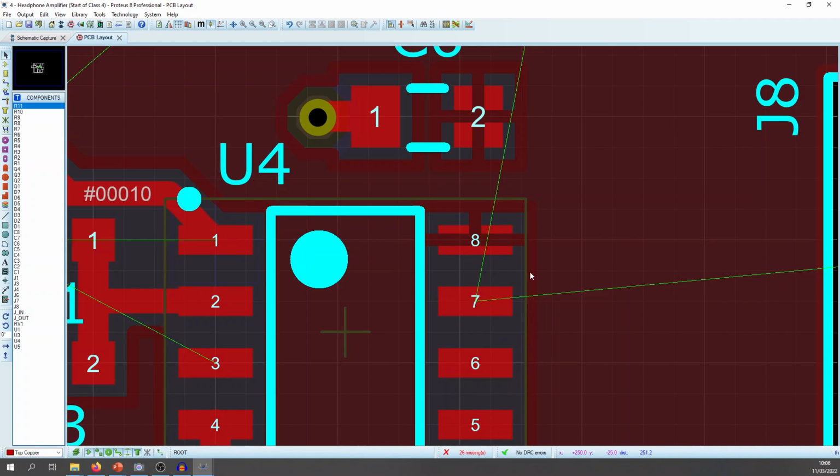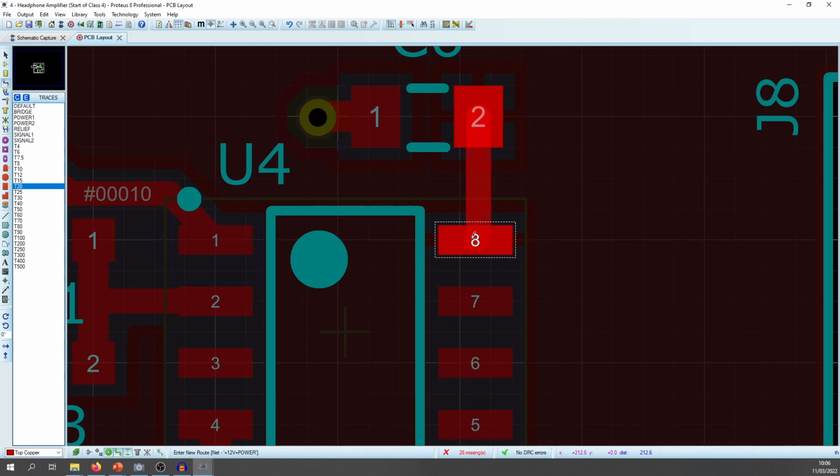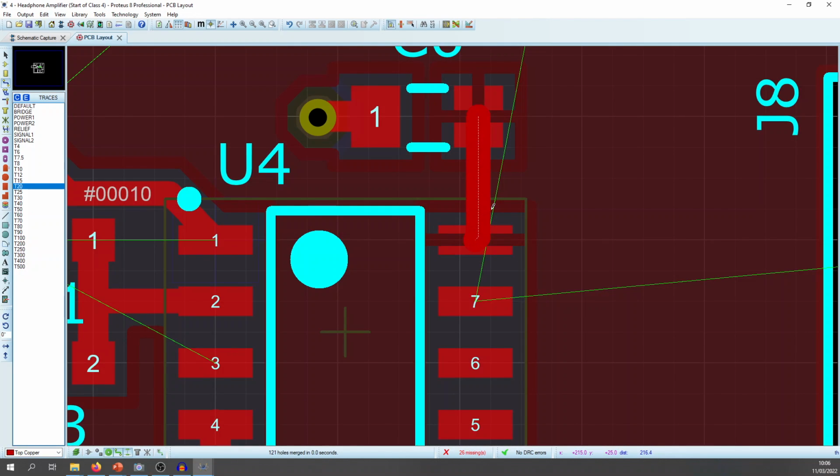Pin 6 doesn't either. So any pin that's on the 12 volt connection, that's got a 12 volt power connection, is going to automatically connect. Oh, I see. I haven't done that in Proteus. It's already connected because of the schematic. Okay, gotcha. So I'm putting a track there only to increase the thickness slightly, to lower the inductance slightly. Right. Okay.